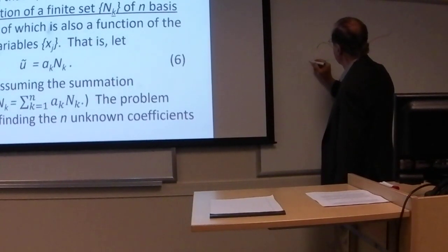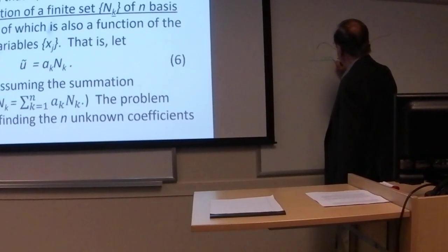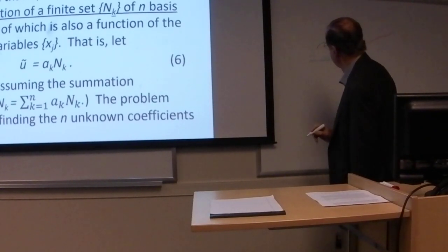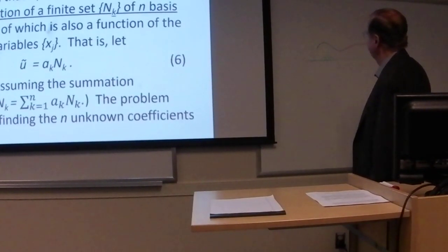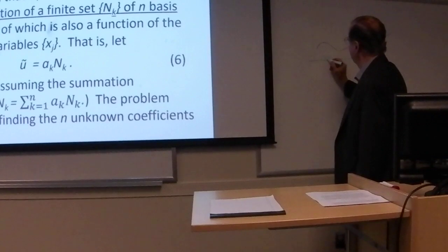This is 1 and this is 0, and so the basis functions turn out to be what are called tent functions, piecewise linear functions over a limited domain. These tent functions assume the value 1 at the node and 0 at the neighboring nodes in each case.